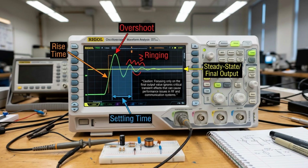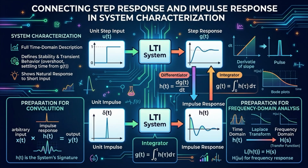A common mistake is focusing only on the final output value and ignoring transient behavior. In many RF and communication systems, rise time, ringing, overshoot, and settling time can significantly affect performance even when the final output appears correct. The study of step response naturally connects to impulse response and system characterization. Since impulse and step responses are mathematically related, understanding both concepts provides a deeper understanding of linear system behavior and prepares engineers for convolution and frequency domain analysis.